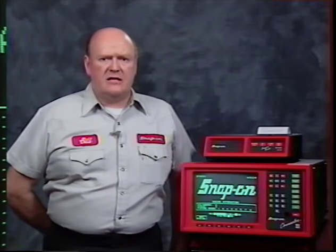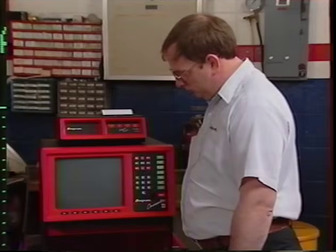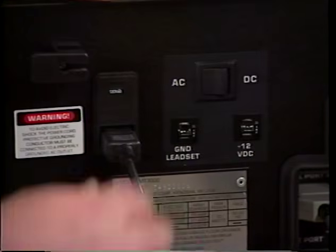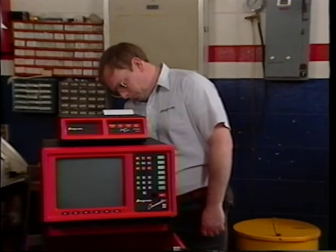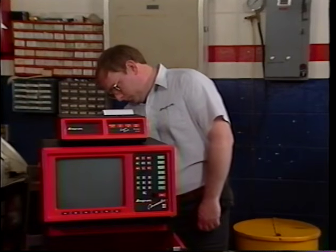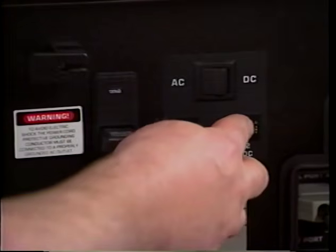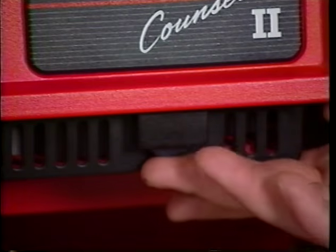The Counselor 2 is built to last and work reliably. But if something goes wrong, let's look at some of the things you might do to correct the situation. First of all, if the screen is completely blank, press Reset to restart the scope's computer. Check to see if the scope is turned on and plugged in. Is the power source working properly? Is the cord connected securely to the scope? Is the fuse okay? Is the voltage correct? Is the brightness control turned up high enough?